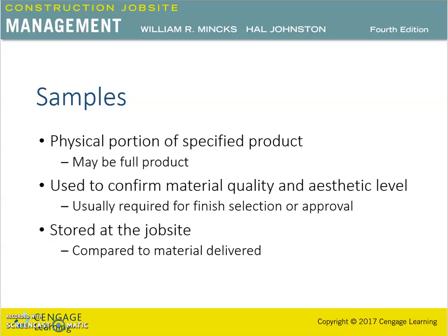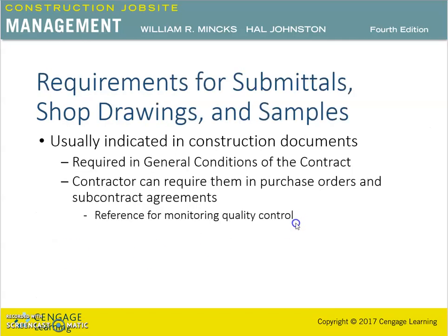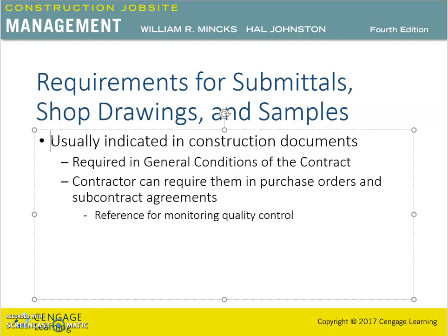Okay, so now let's discuss some requirements for submittals, shop drawings, and samples. So the construction documents usually indicate which product data, submittals, shop drawings, and samples are required by the architect for a particular project. The contractor can require these in purchase orders and subcontract agreements, whether or not they are specified in the construction documents.